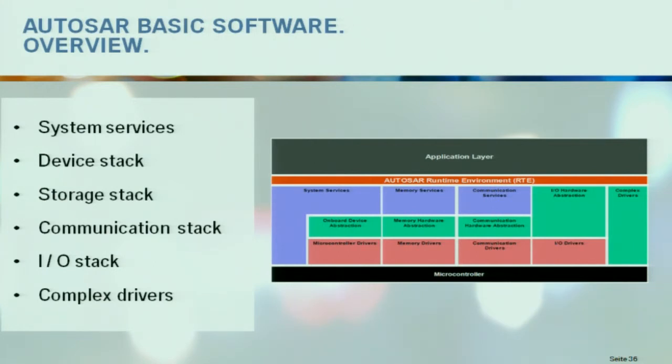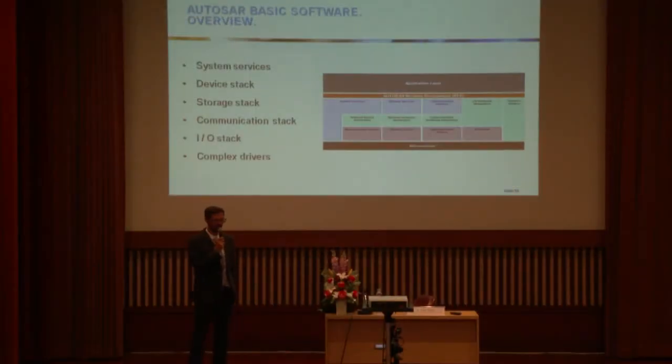The other use case for complex device drivers is if you have old software, which is legacy code, meaning legacy code which is not AUTOSAR compliant, and you want to reuse it. Then you put it into a complex device driver and it can be used in an AUTOSAR environment.